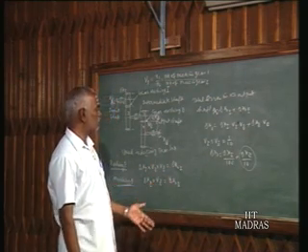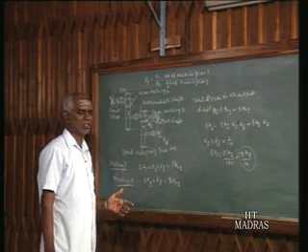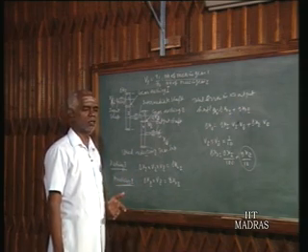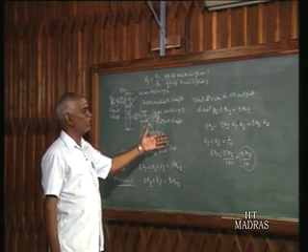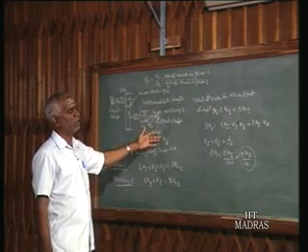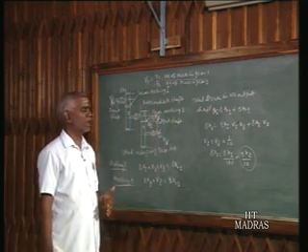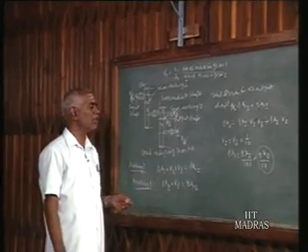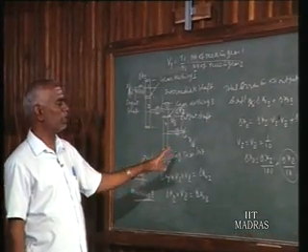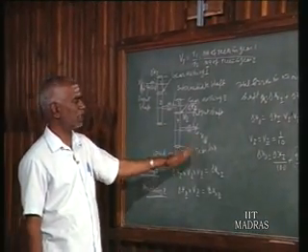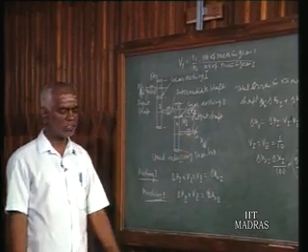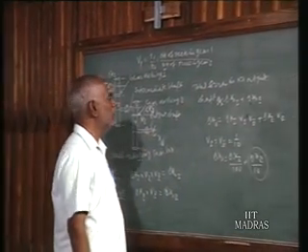So we have seen for friction what methods you should adopt to reduce the effect of friction or eliminate the friction, by using the repulsive force of a magnet or the taut band bearing, and for play how to eliminate the play in the case of linkage mechanisms and in the case of gears. Next one is temperature, how to reduce the effect of temperature.